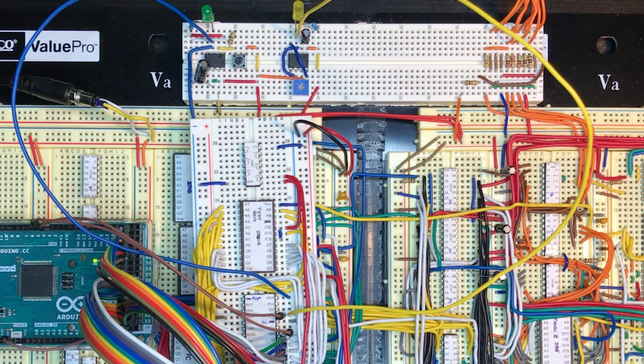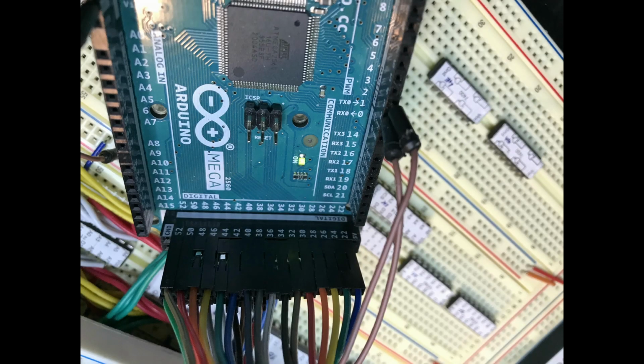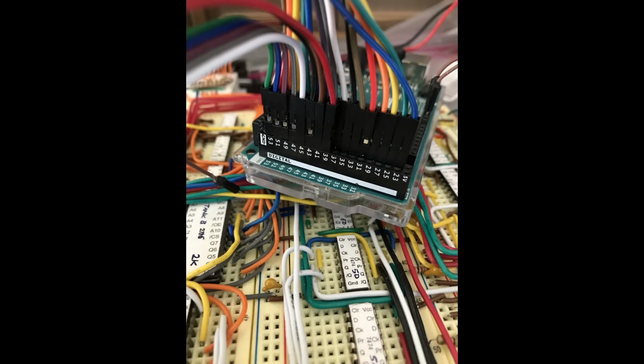You can see that the yellow long wire is coming from the clock circuit at the top of the screen and goes into the CPU clock. The long blue wire is the reset and goes to the reset pin of the CPU. The address pins go from 52 down to 22 on the Arduino. Pin 52 connects to the A0 pin, and so on until pin 22 on the Arduino connects to the A15 pin of the CPU. Pins 53 to 39 connect to the CPU data pins D0 to D7 in that order.